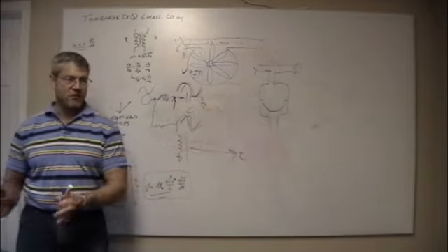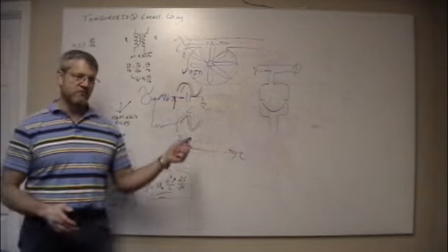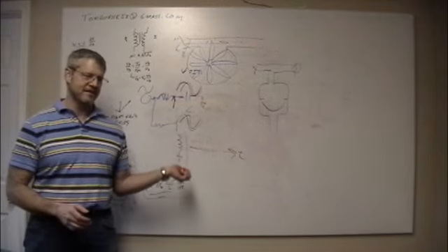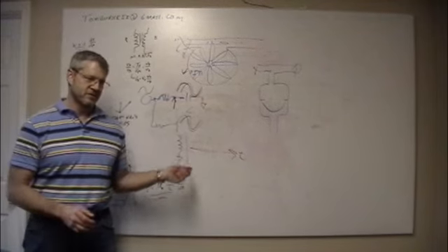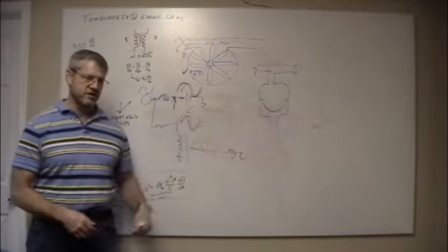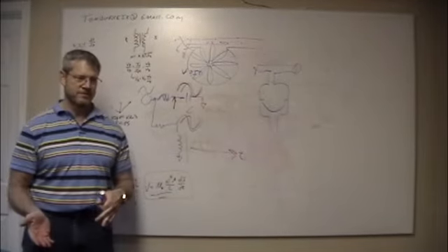Factories get charged for power factor, and it's called VARs, volt amp reactive. So when you start talking about AC, you're not talking watts anymore, you're talking volt amps.